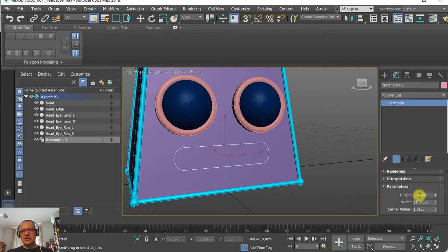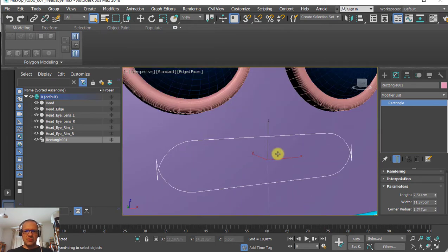And if I divide it into 2, that means if I reach somewhat 1.26, it will start to overlap. Now, this is what I want to avoid. Let me show this. Now it's emphasized. It's way over 1.5. So even 1.5, that's half of 3. And as you can see, this is really hard overlap. I don't want to create an overlap because later on it can mess my geometry.